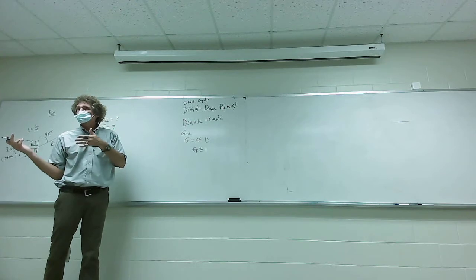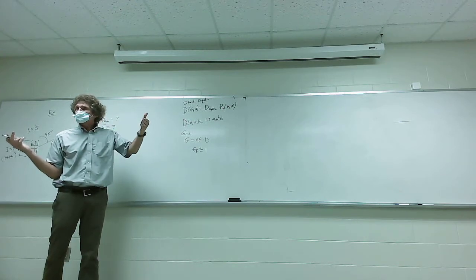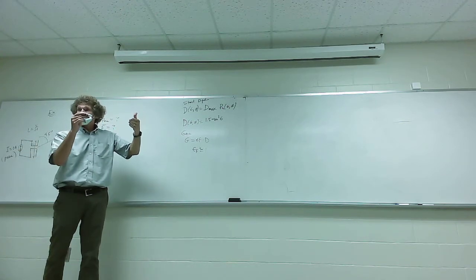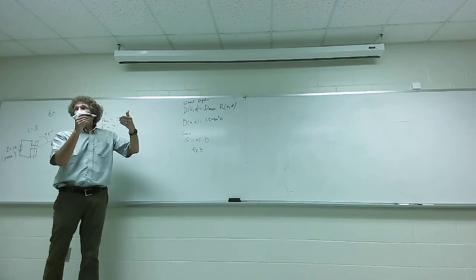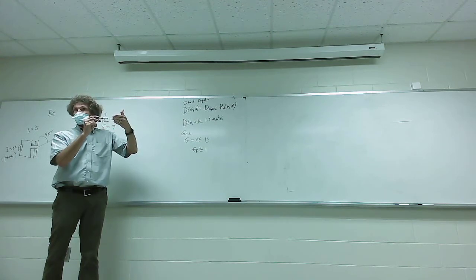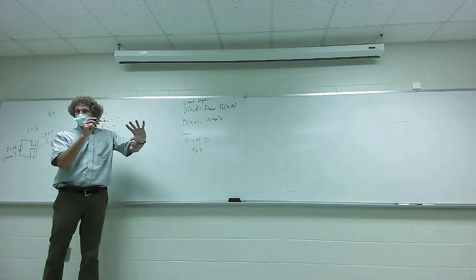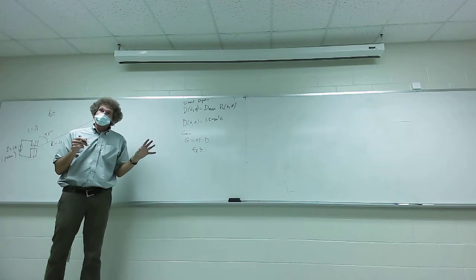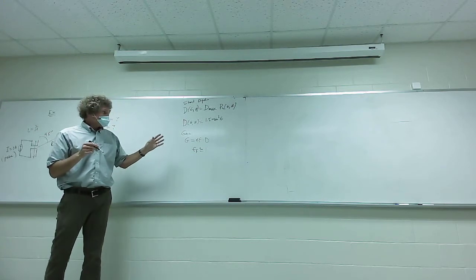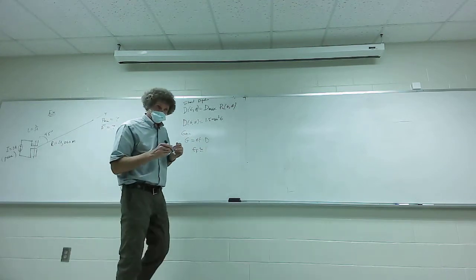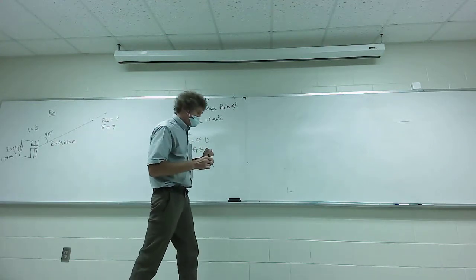And by that it means the copper losses. You all know when you pass current through a wire, whether you like it or not, there's some resistance, and therefore there's I squared R heating. Y'all with me on this, class? You can't get rid of it. But if that is small compared to the actual radiation resistance losses, then you neglect it, so they use gain and directivity interchangeably. But this is the symbol for gain.